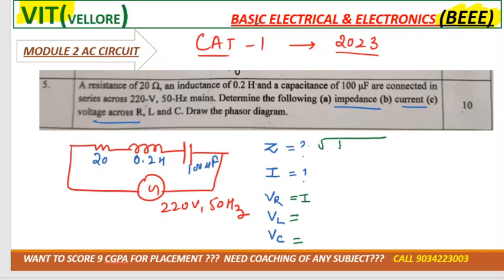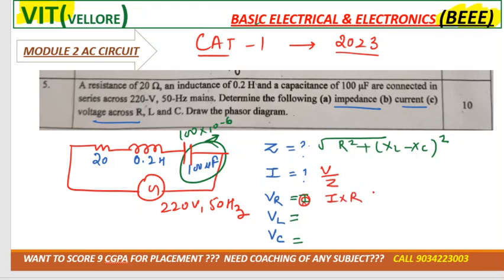So Z is equal to root of R square plus (XL minus XC) whole square. For XC, you need to convert the 100 microfarad into 100 into 10 raised to power minus 6, right? I is equal to how much? I is equal to V over Z, not R. VR is equal to I into R. VL is equal to I into XL. XL you already calculated in Z, right? VC is equal to I into XC, correct?